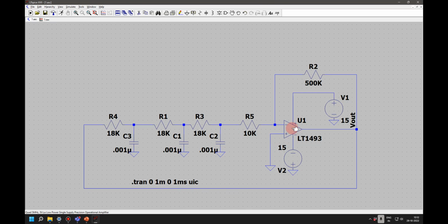So this is with an op amp I have picked up. You can try it out with a transistor. Okay, so in one go you may not get the results. So you should know what is happening. Okay, the RC will decide the oscillation frequency. Then you have to ensure the gain. So initially you can target a high gain so that at least you see a square output. Okay, then finally you can fine tune it.